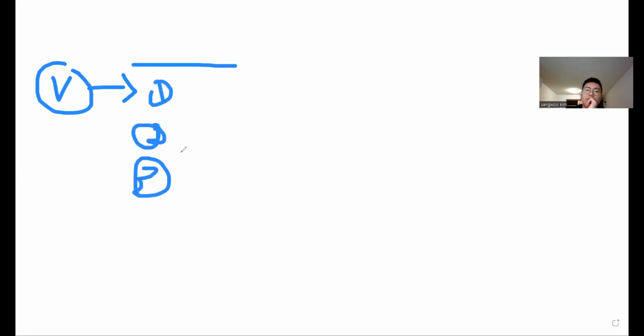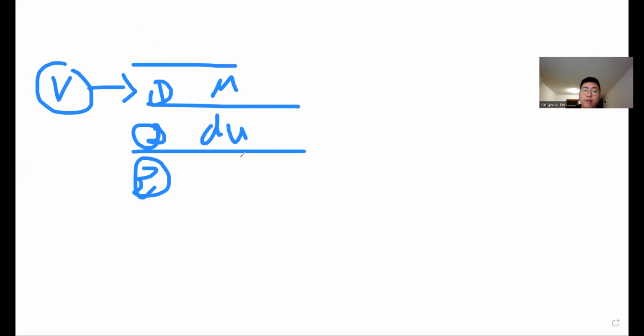I said the switching surge causes insulation damage, right? So there are three variables: the first is magnitude, the second is duration time, and the third is the slope.